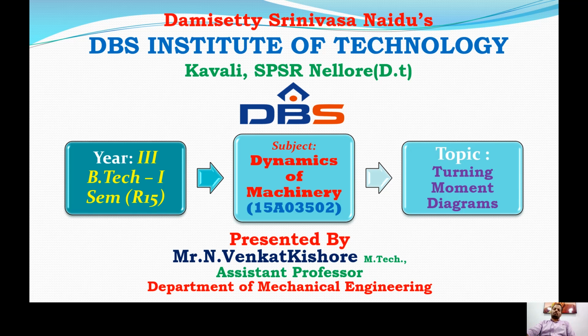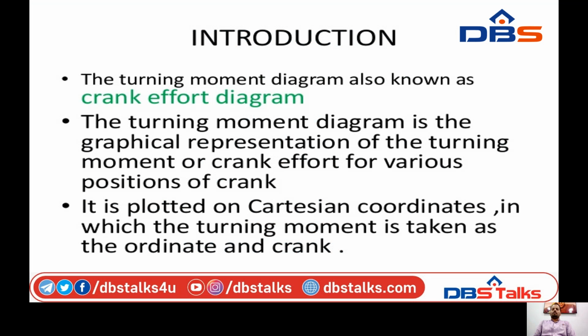Now the topic is the turning moment diagram. What is the turning moment diagram? It's nothing but the turning, or otherwise the motion, of a crank. The turning moment diagram is also known as the crank effort diagram. It means that while a crank is rotating, how much energy is developed by the engine and how much energy is useful to the machine.